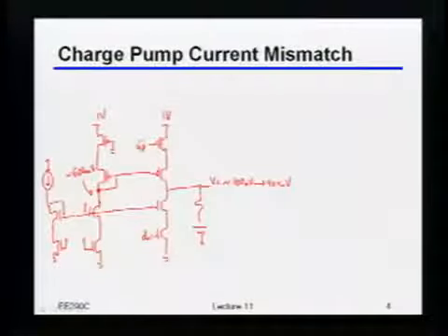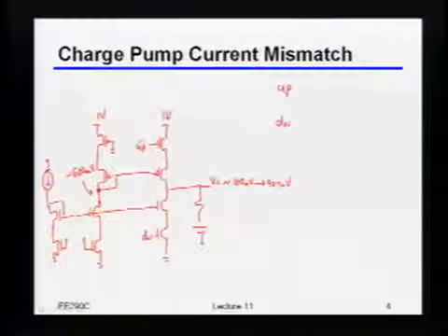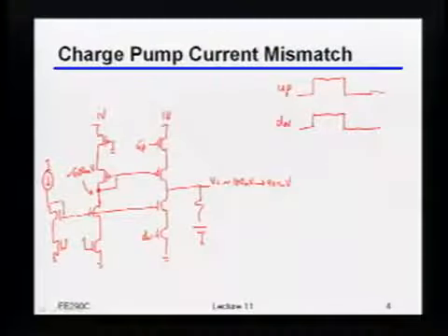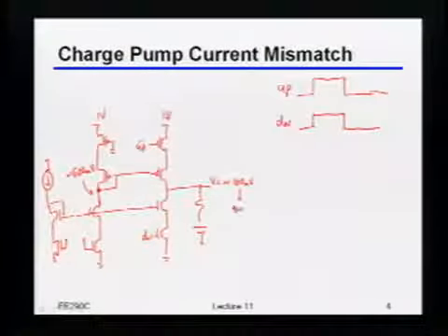So now this actually creates an interesting situation. Remember, we're using this thing to act like a transconductance stage, right? So let's think about what happens if I just take an up and a down signal that are totally lined up. Because remember, for my PFD, there's always going to be some finite width pulse that I use just so that I avoid the deadband problem, right? Let me just move this over so I've got some space. Let's say 100 millivolts and 900 millivolts.